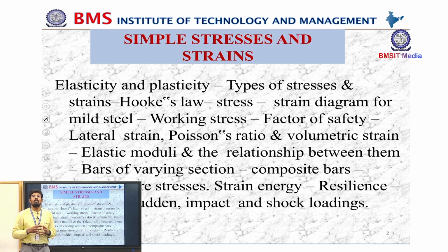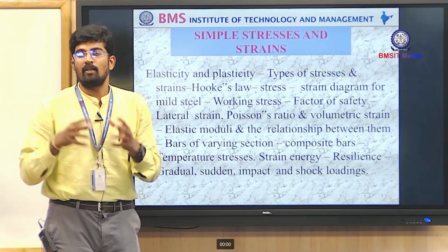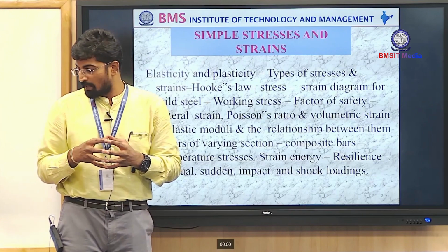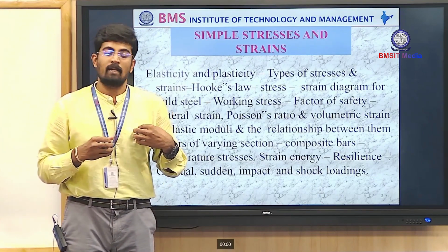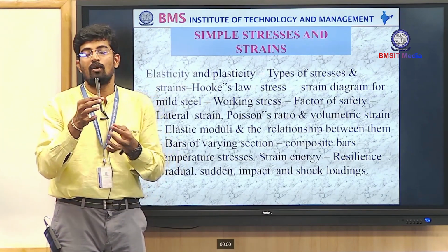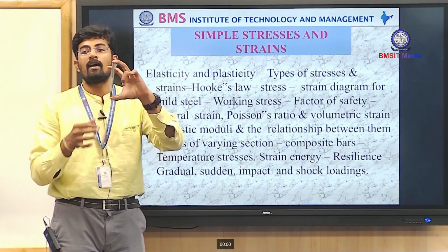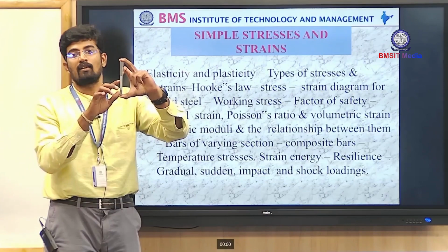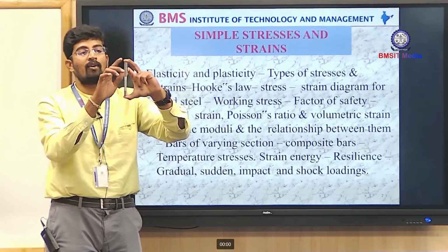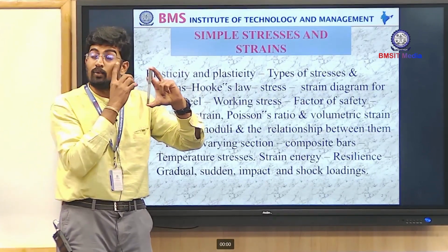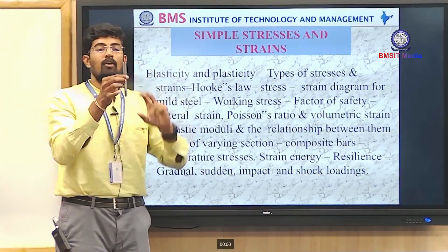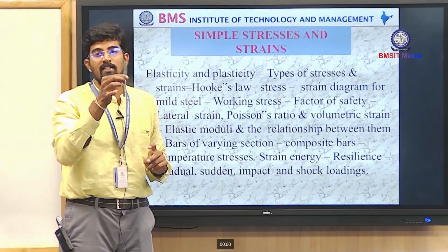We are not going to give the complete load that a particular material is going to bear. Suppose I take some object, this is my pen, which I consider as a column. If I put it through an experimental test and it's going to take some 100 kilonewton, I'm not going to apply 100 kilonewton and design.